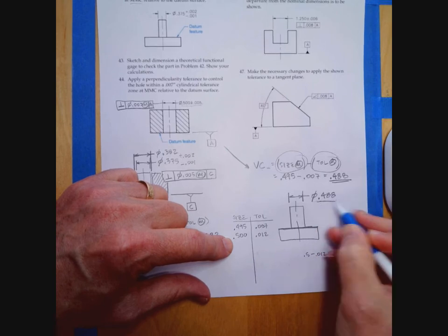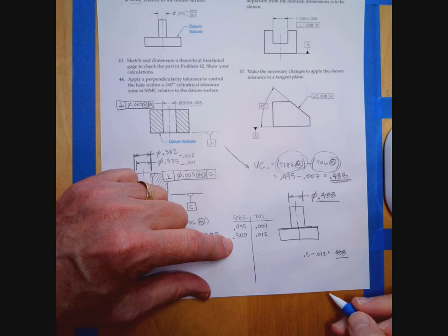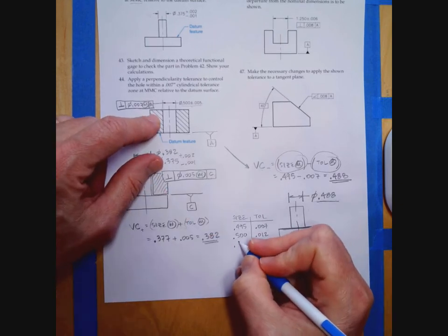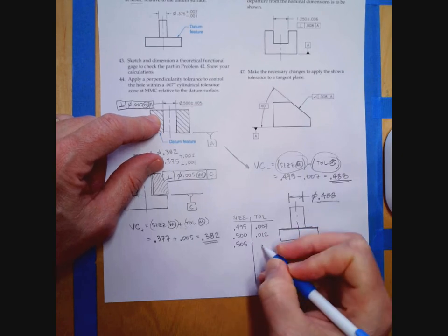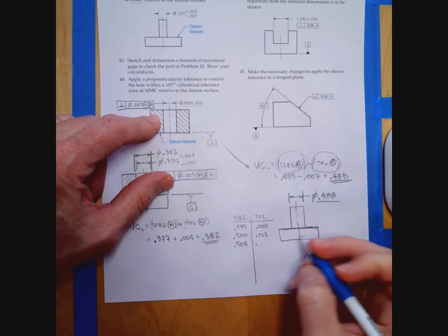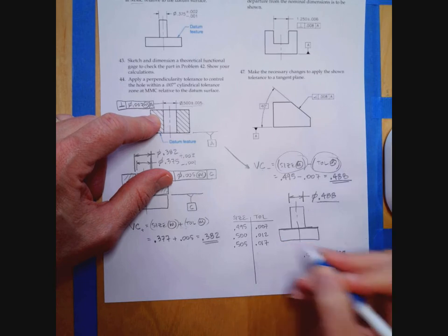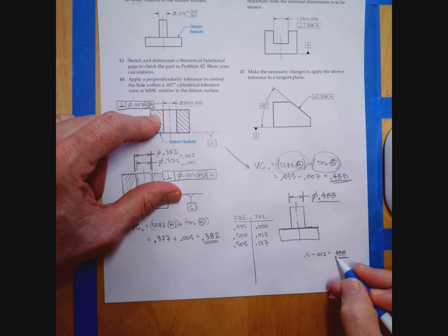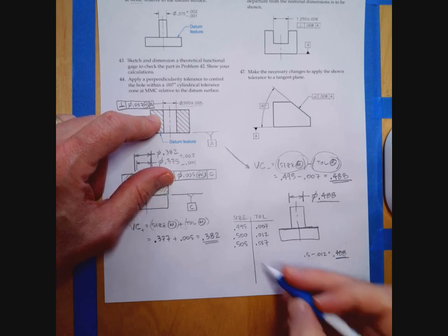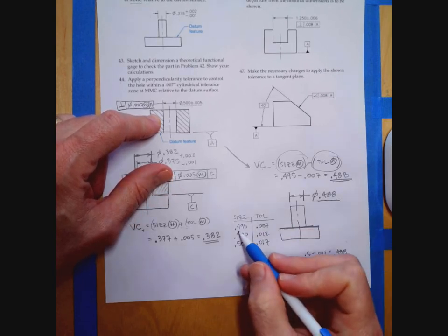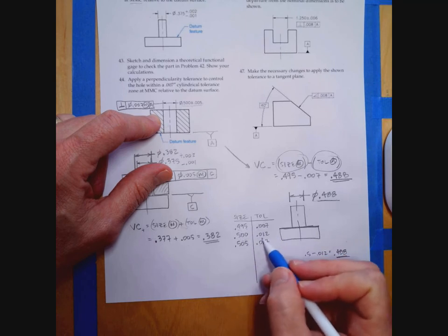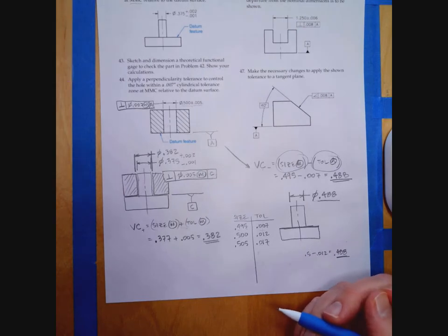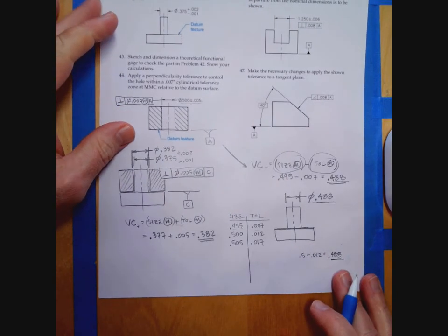And remember, this is a constant. If we go all the way up, if we make the hole at its largest diameter, 0.505, then the tolerance increases to 0.017, right? Because 0.505 minus 0.017 equals 0.488. Okay? So that's a quick little table that you can do. Obviously, the values in between are going to be in between these tolerance values. And we'll do more of this in the next video. Okay? All right, so I'll see you in the next video.